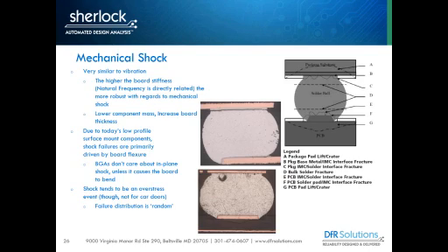It's just sort of the nature of the intermetallic that forms, a tin nickel intermetallic versus a tin copper intermetallic. But you can see here, during a shock event, I can fracture the intermetallic, or I can cause bond pad cratering. If this is a large ceramic component, I may fracture the ceramic. It got a little bit worse with lead-free because now we have a stiffer solder joint that transmitted more stress into the other interconnect structures or even the bodies of the components.